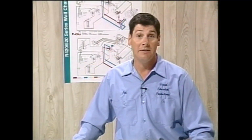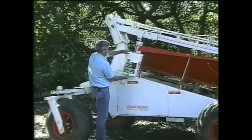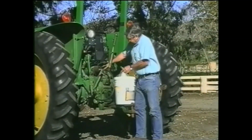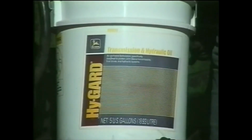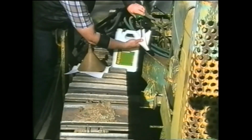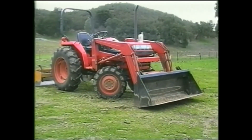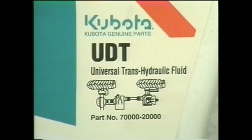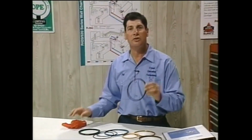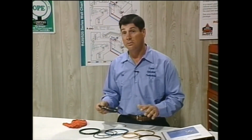Hydraulic oil is highly refined to meet various applications. One machine may have a system with no special requirements for the hydraulic oil, while in another machine, the hydraulic oil must also serve as a lubricant for gears and bearings in the transmission or gearbox. These hydraulic oils might appear to be alike, but they are refined to different specifications. Some hydraulic oils may need to meet high temperature or transmission gear lubrication specifications, while others must be compatible with certain seal materials. Some oils are mineral-based, while others are synthetic or vegetable-based.